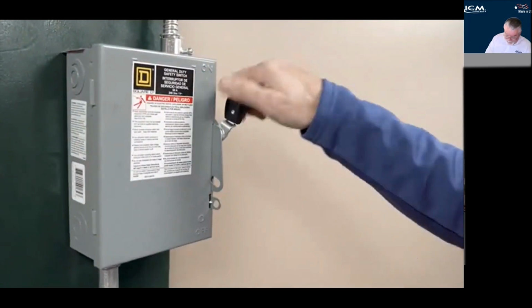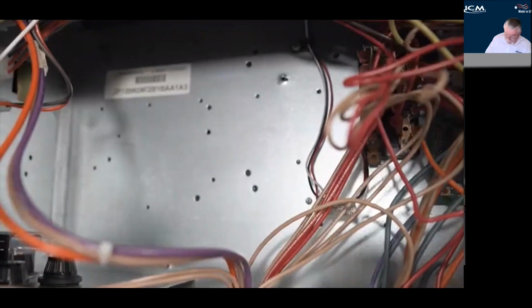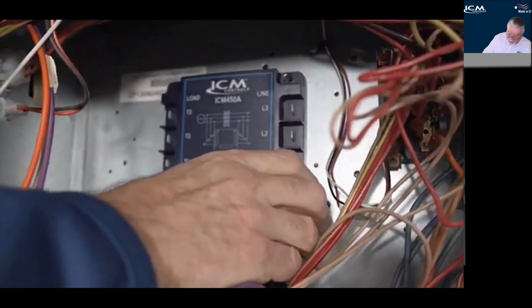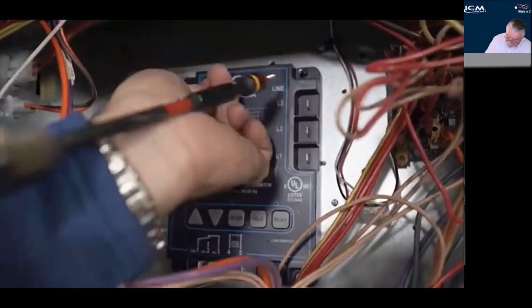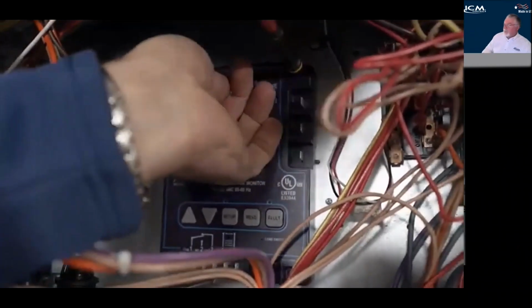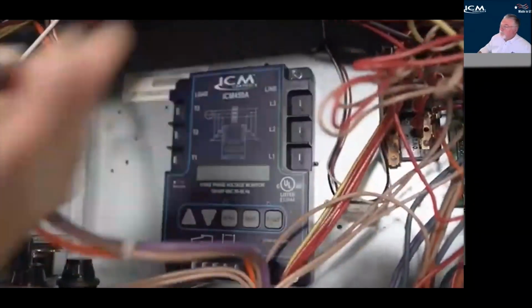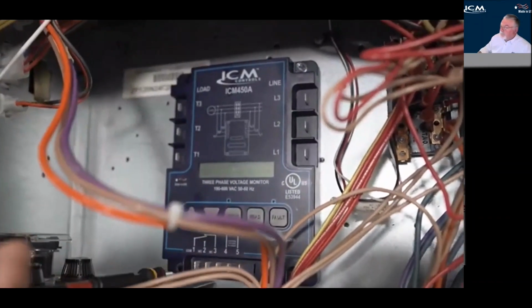Keep in mind safety first, so you want to make sure you turn the disconnect off to the power source for your unit. You want to find a big enough area to set this in comfortably. Get your hands out of the way. Easy to work on, easy to see. The unit does come with self-tapping screws to make it easier to go through the sheet metal.